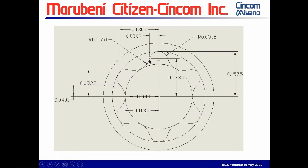And then you would say, here, this is a counterclockwise move, which is normally G3, but since it's reversed, if you're doing the outside, like let's say the tool is on the outside of this, it would be a G3 move normally, so you would have to program G2, and you would go to the number here from this to here, 30 thousandths, and up 133. You'd use that as the X and the Y, or Y and the X. No, this is the Y. The X and the Y.